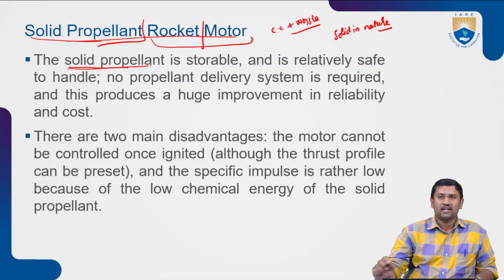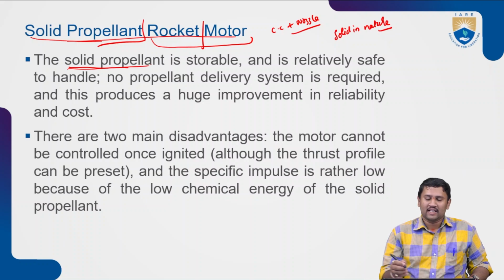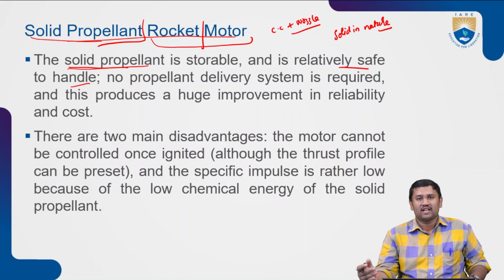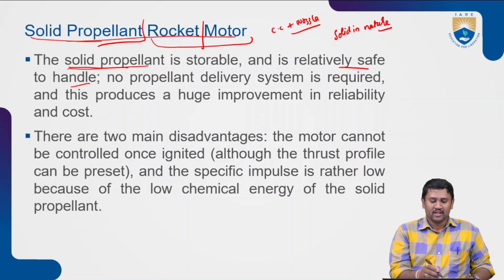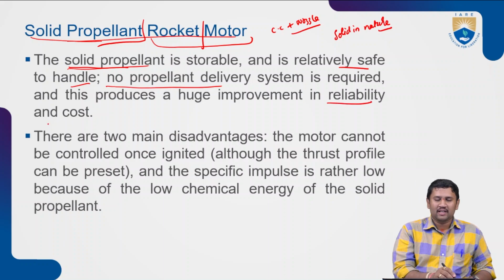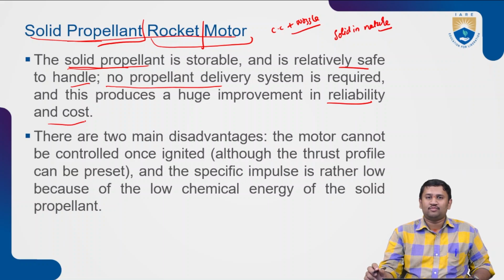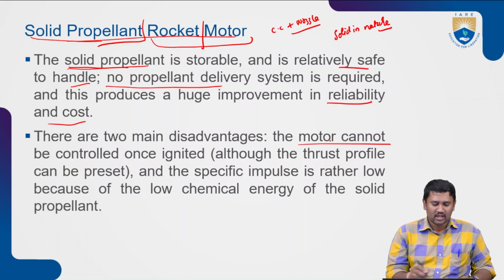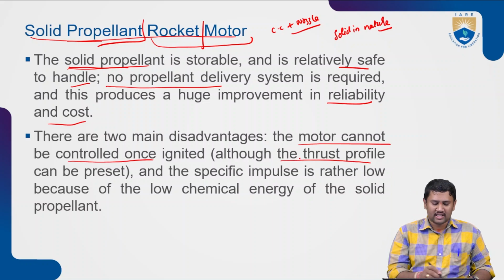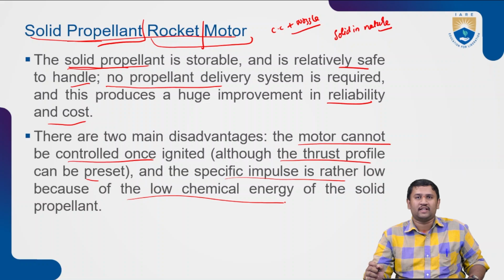Now, why solid propellant? Because it is storable and relatively safe to handle compared to your liquid propulsion systems. We will come to liquid propulsion systems further on. Also, no propellant delivery system is required, which produces a huge improvement in reliability as well as cost. The two main disadvantages are that the motor cannot be controlled once it's ignited, although the thrust profile can be preset, and the specific impulse is rather low because of the low chemical energy of the solid propellant.